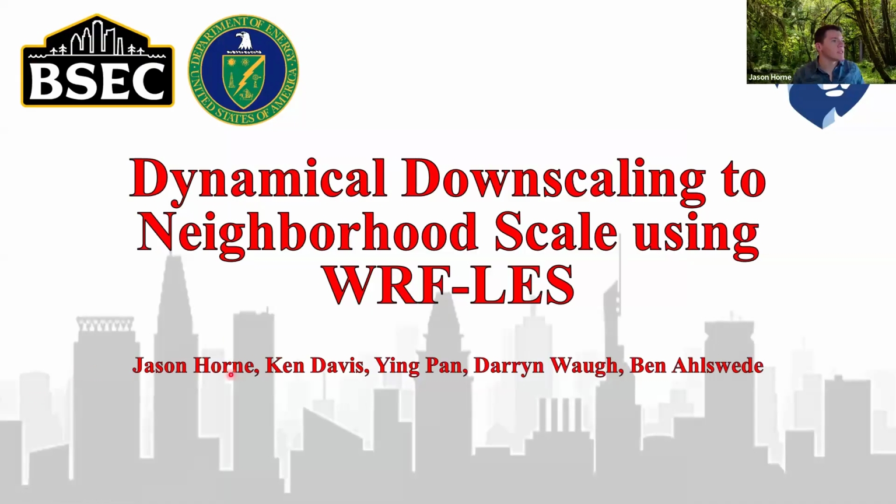So, all right, let's continue with the LES simulation stuff, doing a very similar sort of methodology to what the two colleagues had just spoken about. I'm going to be using WRF LES to downscale from the synoptic to the mesoscale all the way down to microscale at the neighborhood level, and seeing how well we can actually capture neighborhood heterogeneities as validated by observations, right? That's a very important part of this entire framework: you have these simulations, but you also need to back them up using real world observations.